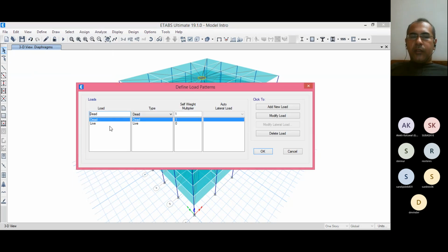In that, all types of loads need to be defined. Right now dead load and live load are already defined in ETABS, they are always there. Let's take earthquake in X direction. Take seismic. Seismic and seismic drift are there. Drift is not suitable for our case. As per the IS code or as per the Euro code, we don't take drift. But if your building is flexible, and your overall drift of the building is limited in the seismic parameter, it will be as per your code.